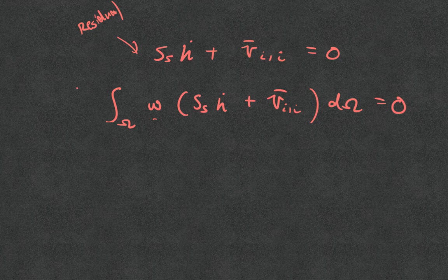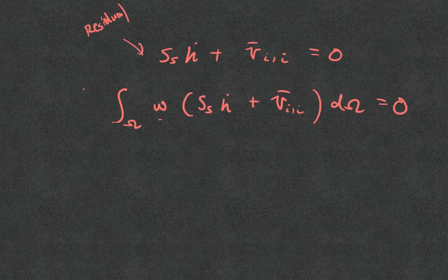Strictly speaking, the finite element equation can come from two formalisms. One is the weighted residual statement, another one is the Euler-Lagrange equations. The Euler-Lagrange equation would be derived in a different way, where you try to find the Lagrangian and then find the Euler-Lagrange equations. Here we will use the weighted residual statement just to make it a little bit easier.